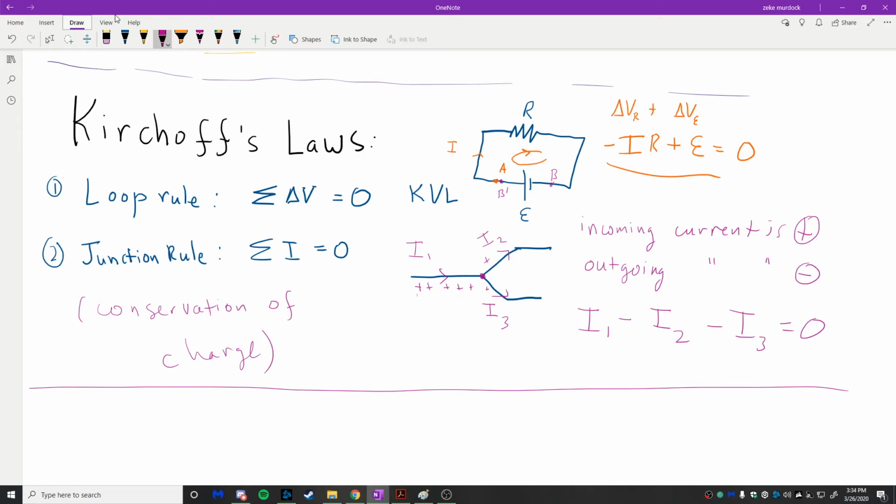Did you guys follow what I was saying? Like if I took a multimeter and connected it to this point and to this point, the voltmeter would read 0. Does that make sense? Because you're basically measuring the potential difference between a point and the point right next to it where there's nothing in between. Now, if there's a battery in here, you're going to get something, right? But you're going to get 0 when you measure the potential difference between 2 points, right?